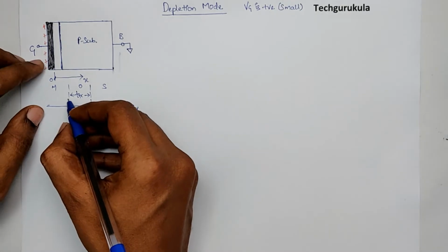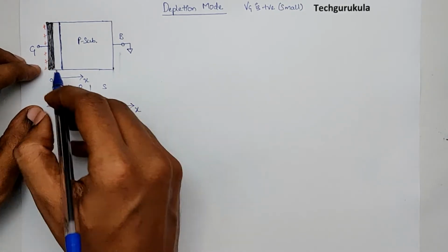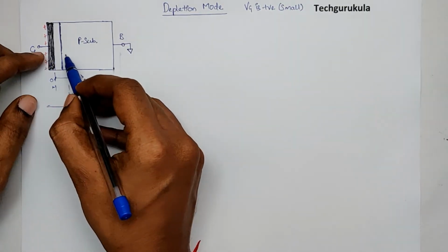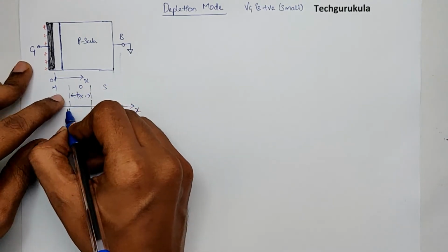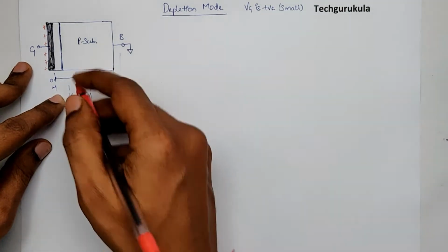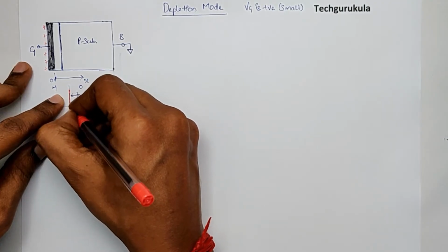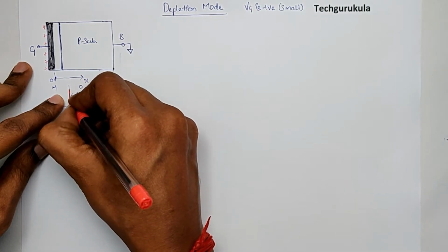Now because there is positive charge at the gate, it would be at the interface of metal and silicon dioxide, because of the electric field they get pulled close to each other. So we have positive charge at the metal oxide interface, which would be like a line here, because there can be so many energy states at a given point on metal.